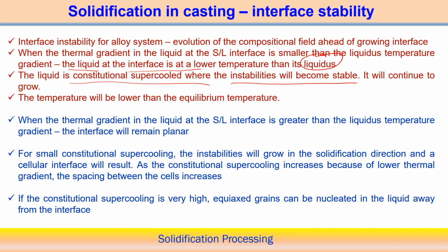But I mean to say that when the liquid at the interface is at a lower temperature than the liquidus temperature, it creates a more stable situation. Even though there is constitutional supercooling, the interface becomes more stable in this particular situation. In that case the temperature is usually less than the equilibrium temperature.